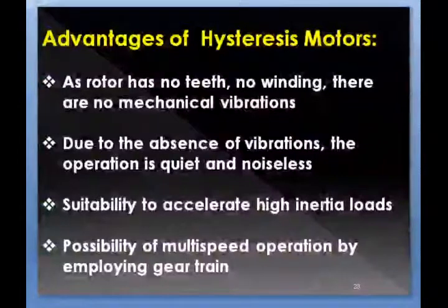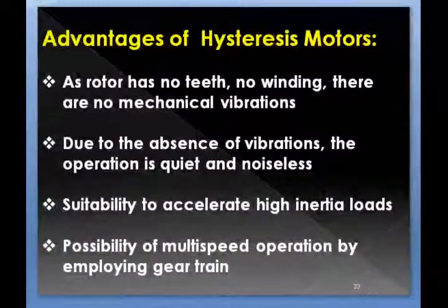We discuss the advantages of the hysteresis motor. We see that the rotor has no teeth and no winding. It is smooth, so there is no vibration and noise.